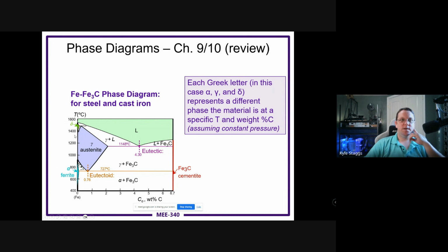In this case, for the austenite side, there's another phase transition as it continues to cool and recrystallize. There are these two different phases, and the austenite-only phase disappears at that point. So the lowest temperature point tells you the composition for the eutectoid.